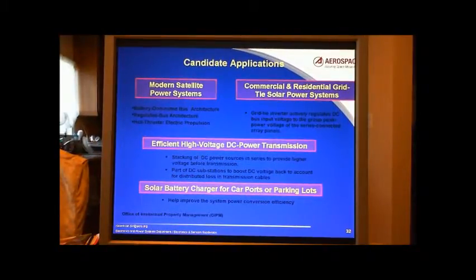The same power system architecture of series connected power sources is also applicable to grid-tied inverter applications. In this application, the grid-tied inverter actively regulates the DC bus input voltage across the power sources to track the group peak power voltage of the series connected solar array panels. The third area of application is efficient high voltage DC power transmission, by stacking DC power sources in series to provide higher voltage before transmission over a long distance.